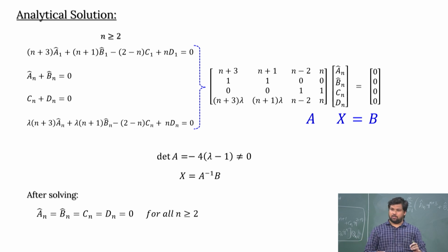Now you will recall when I told you in the H equation solution, only q1 exists, and all other qn vanished. That is why in the Stokes flow over a sphere problem, we directly assume our solution is f of r times sin square theta. That sin square theta is nothing but q1. You understand why we are taking this? This is the full process you have to do, then only you will get the final form.